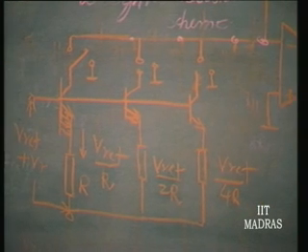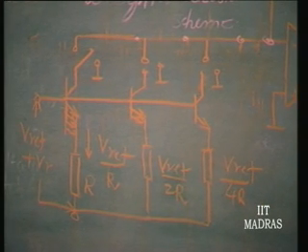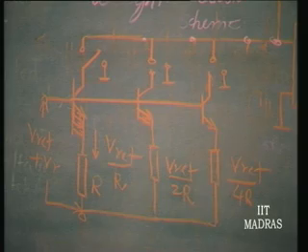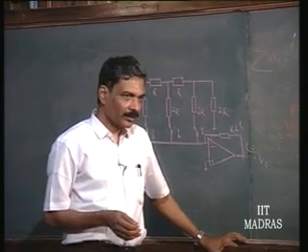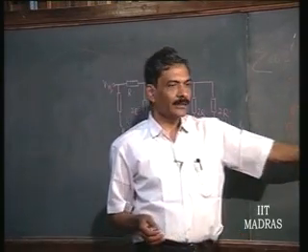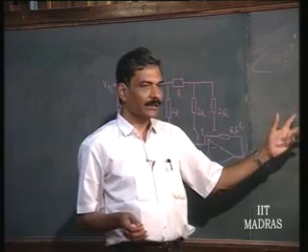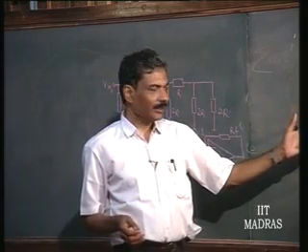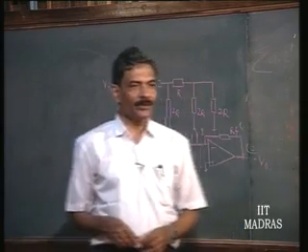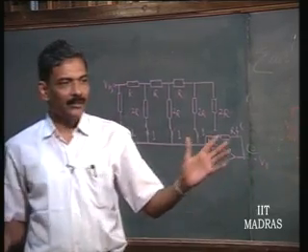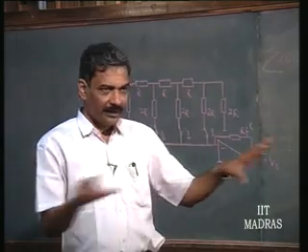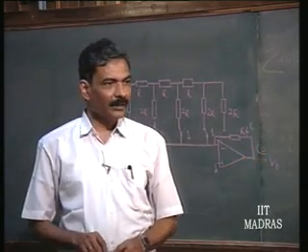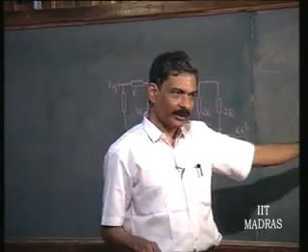So, you can see a nice 3-bit converter using current sources which are being switched, and the areas adjusted accordingly, so that the compensation is exact. And this is the internal circuitry of most of your converters. This is done for 3-bit, but you might have some 12-bit or 8-bit converters. You can see the circuit diagram given in the manual, and it will look exactly like this.